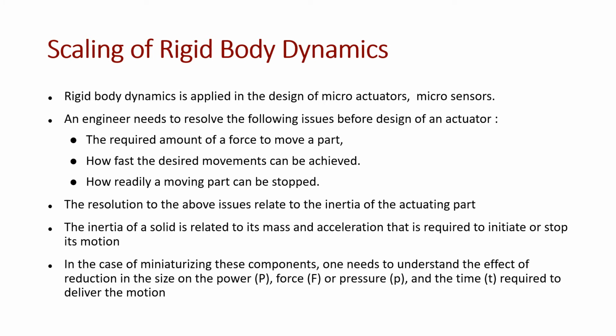Now, in order to design micro actuators and micro sensors, the principles of rigid body dynamics have to be applied. Before the design of an actuator, an engineer has to resolve issues like the required amount of force to move a part, how fast the desired movements can be achieved, that is the timing, and how readily a moving part can be stopped.